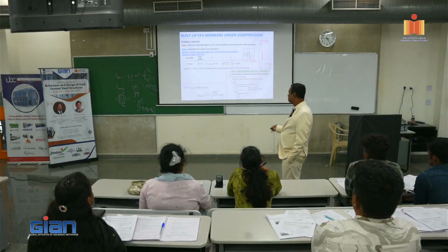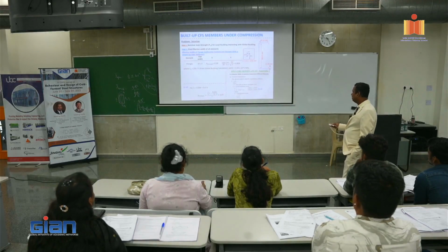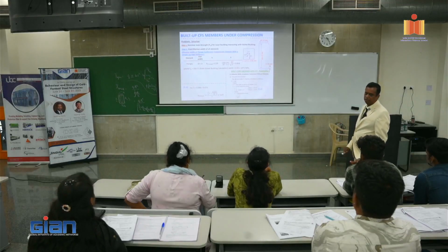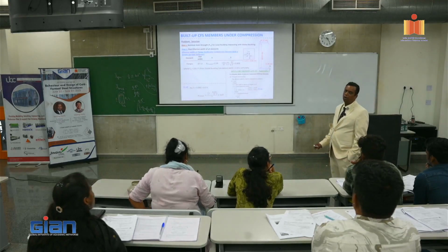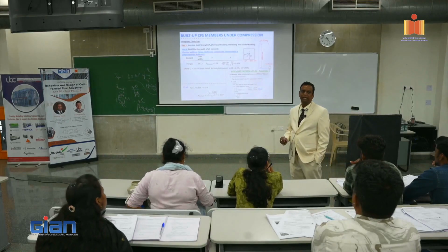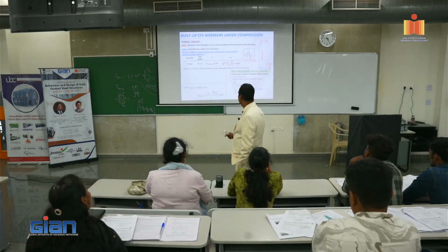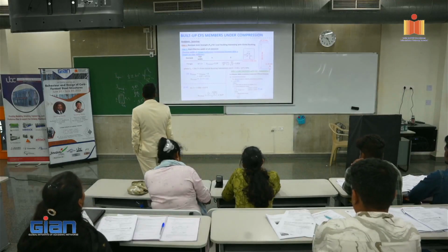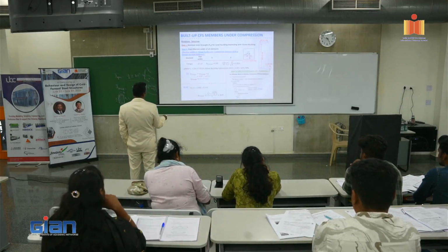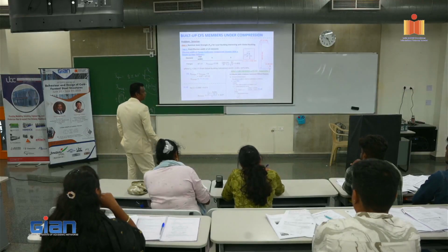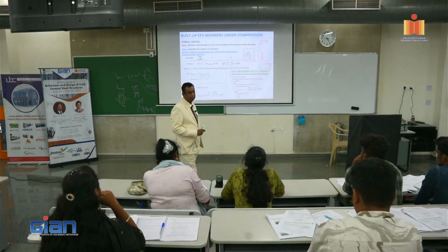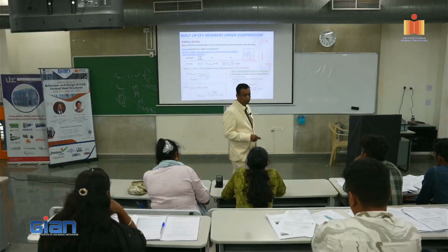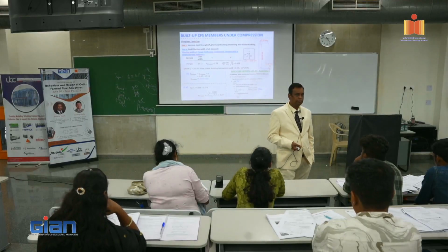So you use the reduction factor, you get a value of 0.87. Which means that 87% of your flange width is effective. So what is your flange width? 67.12, right? So 67.12 into 0.87 is 58.39 is effective, right? Now we have done this one. What else do we need to do?